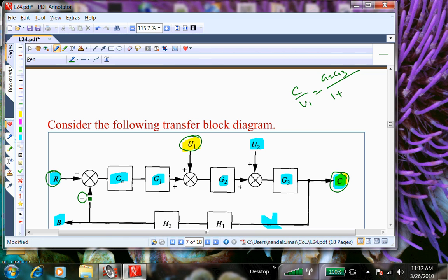The feedback here is coming here. The loop is going back from here, right? So this is a negative feedback. So here you are adding and subtracting. Whereas these are just disturbances. The disturbances are added. Both of them are added. But this is not part of a negative feedback. So the thing that one could get confused here is because I have both pluses here, how does that affect the transfer function? You need to do the algebra to see that it does not affect the sign at all.